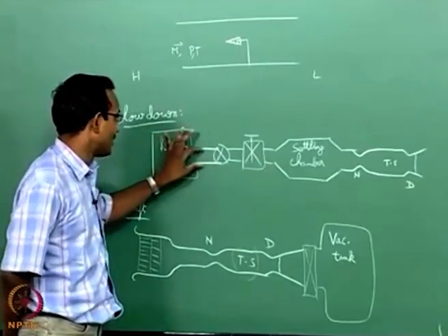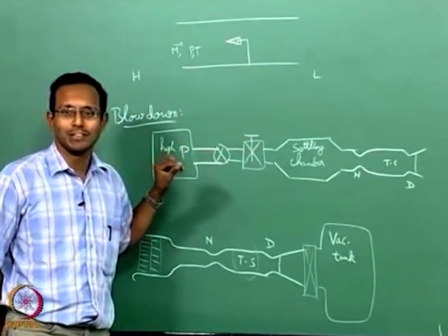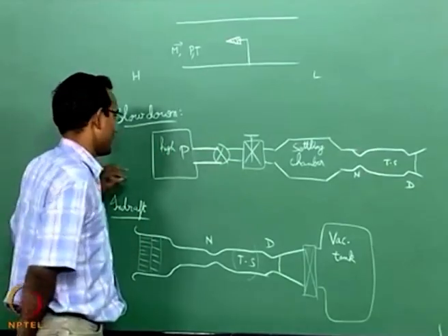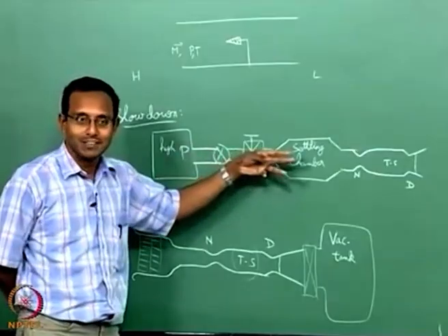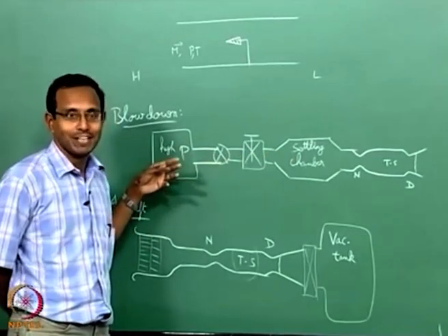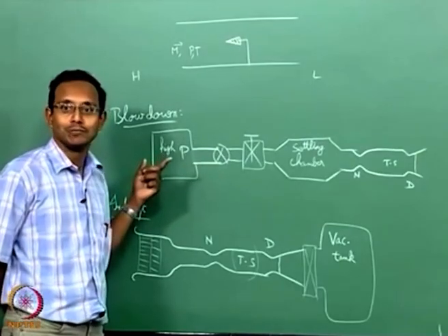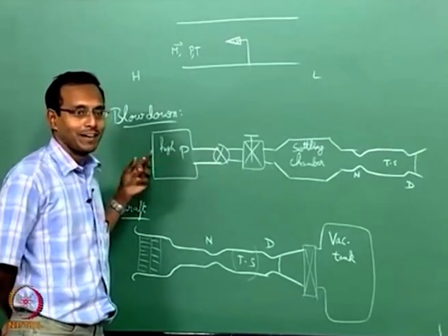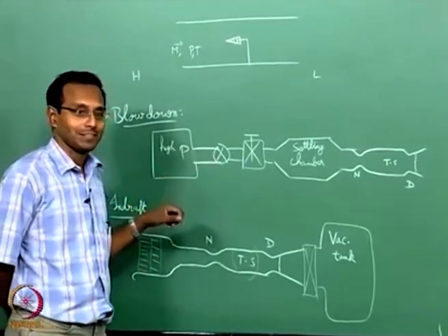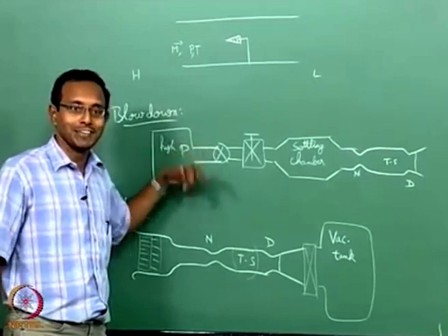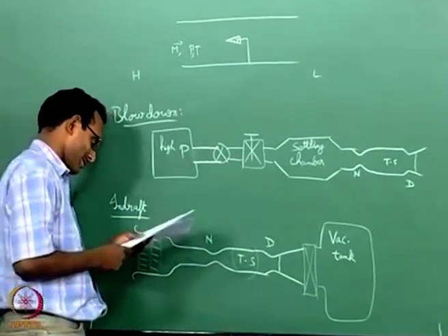So, my walls and the tubes are all going to be a little colder, this is called the Joule-Thomson effect, I believe. Okay. So, that will start happening, that is one thing, and if the pipes are very small in size, you will have more effect of it. I have had a case where I had icing on top of my stainless steel tubes, okay. And of course, my data was all wrong, because my T naught, what I assumed was room temperature, okay. But that is not the case if there is icing on top of the tubes. Okay. So, you should be careful about that also in there.